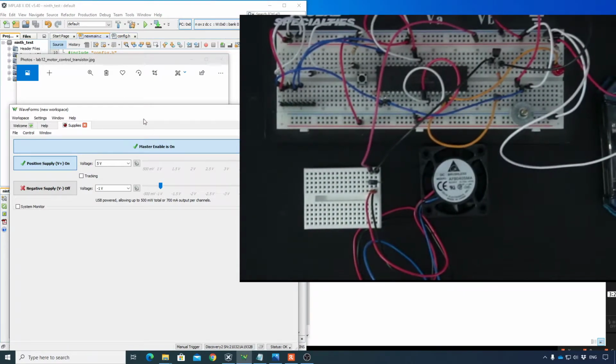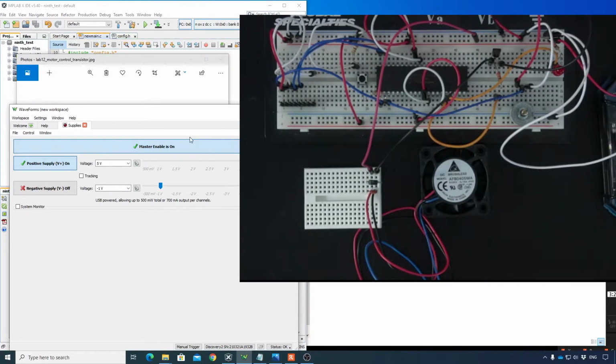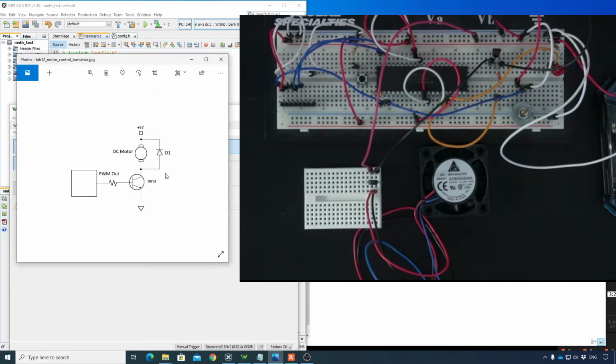So this is pretty much my circuit. What I did is I added another capacitor in parallel here, and that capacitor just served as a filter. Whenever there's a spike, you can't have really huge spikes up and down, and that triggers the protection mechanism of my power supply. So you might have to use that capacitor, you might not, depending on which power supply you have. Mine could not, so I just connected that capacitor there.